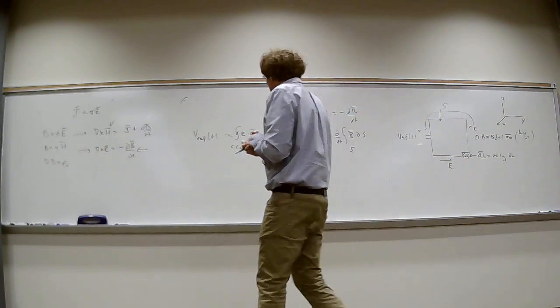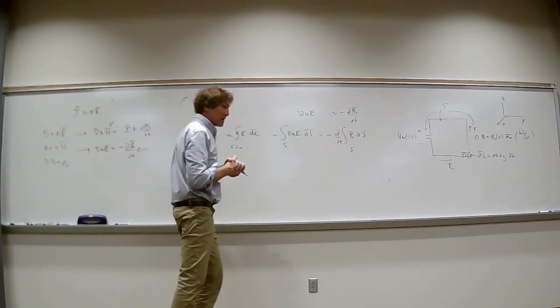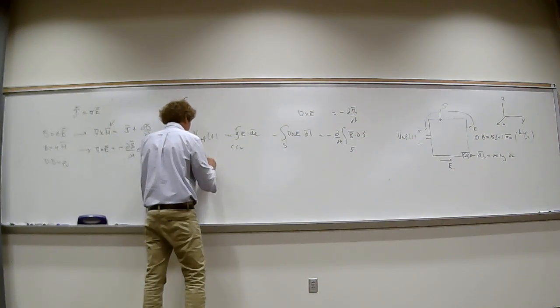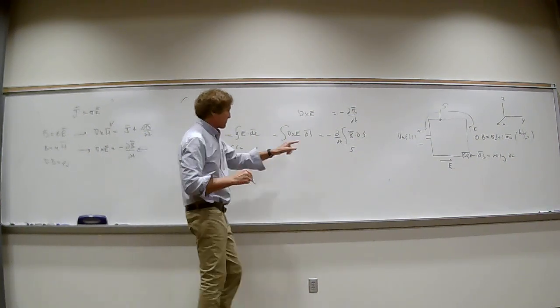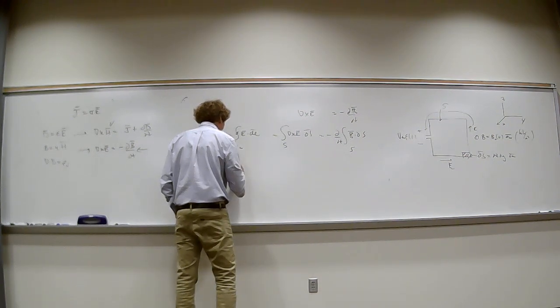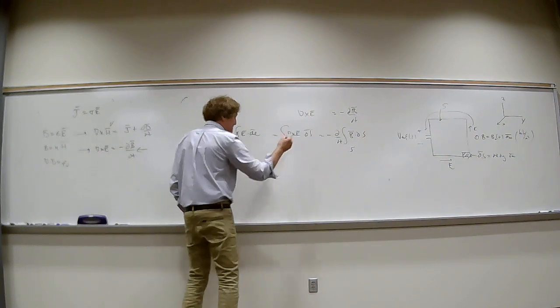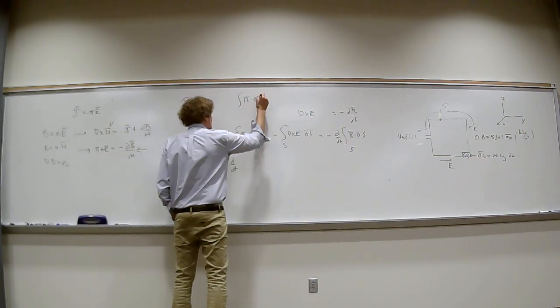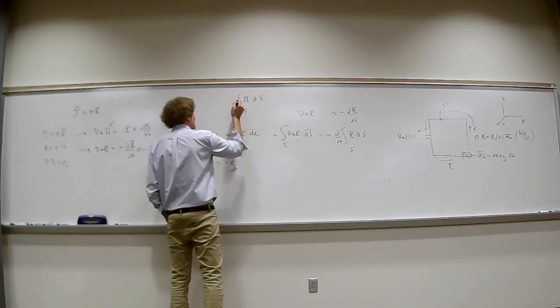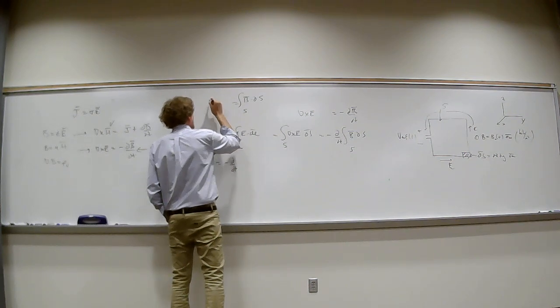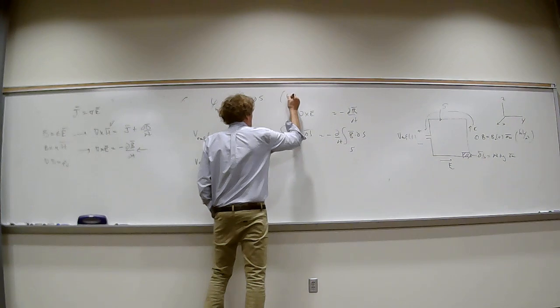So if you get this right here, you'll see that the V_EMF of t is really, now I'm going to jump right over here, minus d/dt of the integral of B dot ds. So what is the integral of B dot ds usually shown as, or we have talked about? That's the magnetic flux, psi magnetic of t, and the units are Webers.